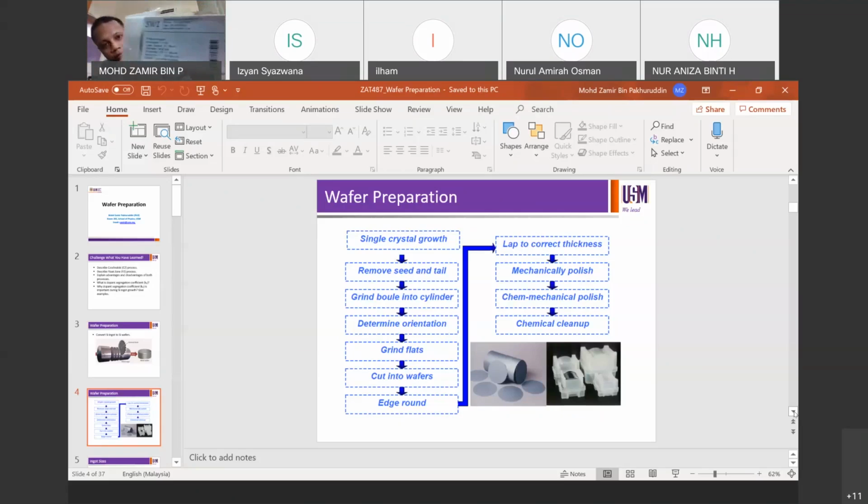You can see some labels on the front side. It's Semiconductor Wafer Incorporated. You can see the label there: wafer resistivity, wafer type, orientation, what else? This one is 2-inch, 50 mm, 5 cm, with a short flat, boron as the dopant.